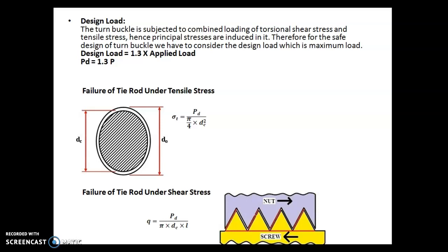Okay, so generally in exam, this data is given in the question. Once in step 1 you calculate the value of DC, suppose the value of DC is equal to 16.5 mm, then you have to see the design data book. But in general, this required design data is given in the question. So check the value of DC, that is core diameter, in the table.